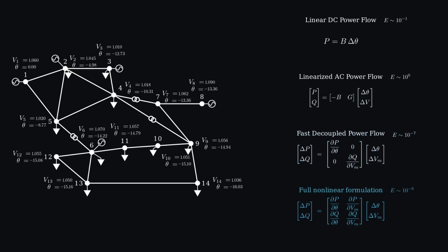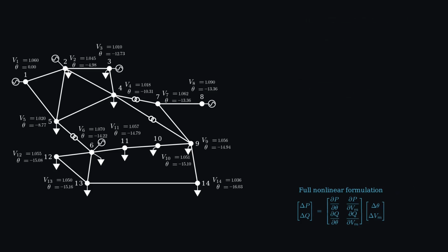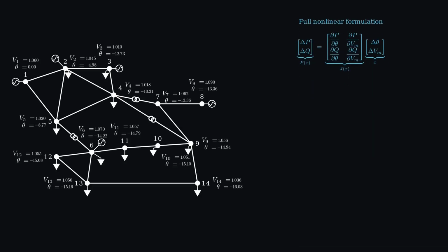Finally, the full nonlinear power flow formulation tackles the original equations without approximation. Although computationally more demanding, it provides the most accurate results and is essential for detailed operational planning, studies involving reactive power constraints, and grid code compliance assessments where precision and model fidelity are critical. To solve the full nonlinear formulation, a range of numerical algorithms are available, each with its own characteristics and advantages.